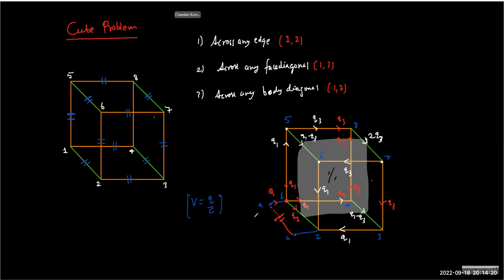Can you see the isopotential points with respect to junction 1? So 1, 4 and 1, 5, so the isopotential points will be 4 and 5. Similarly, the other pair will be 3 and 6. Do you see 3 and 6 having the same potential?